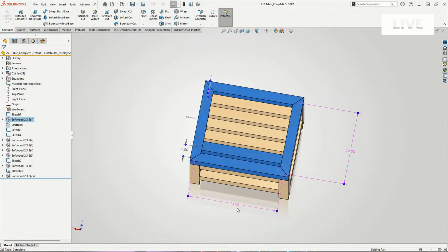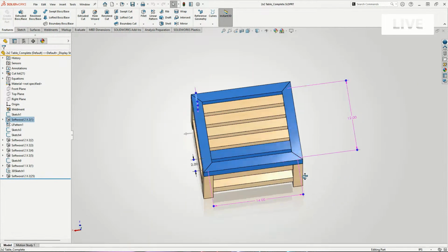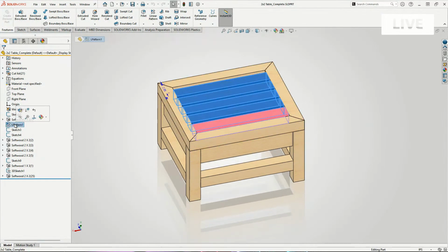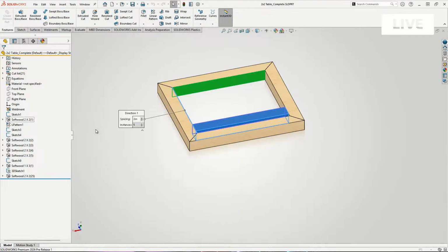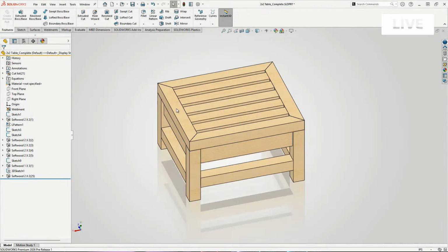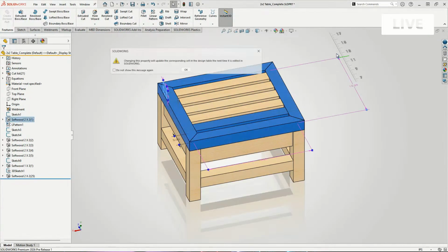We're going to have some dimensions. I don't even have any global variables or anything like that going on here. Inside, there's a pattern. This is the only thing that SOLIDWORKS is doing, where I'm just saying, hey, do an up to reference. So patterning 1 2x2 and just saying go to this face. And no matter what, space them at 2 inches. Because I'll do 2-inch increments, we'll get nice spacing. So I'll show you what that looks like. Maybe this better explains it.